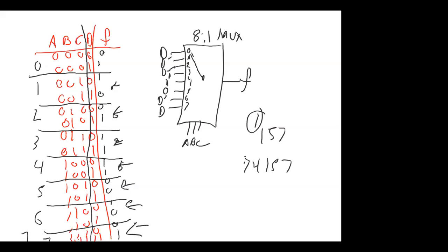And in fact, it refers to the entire family. So you could get an S for a Schottky or an LS for a low power Schottky, or you can get ALS for advanced low power Schottky, or you can get HC for high speed CMOS. They go on and on, but they all have the same pinouts. They all have the same geometry. They all fit into the same breadboard. They just take different amounts of power and run at different speeds.